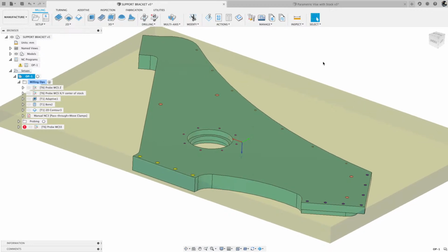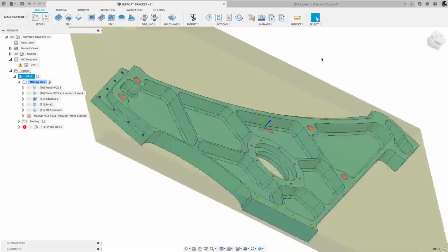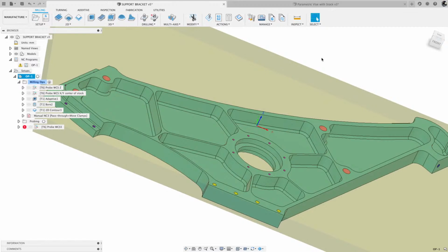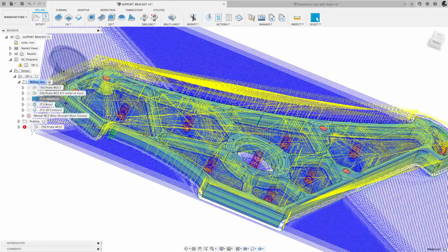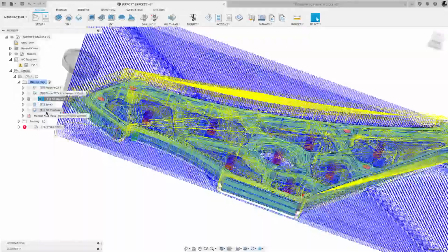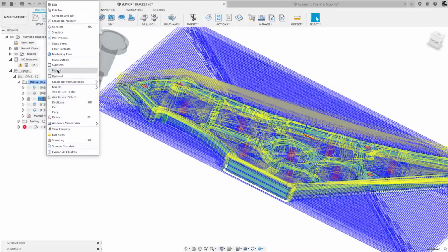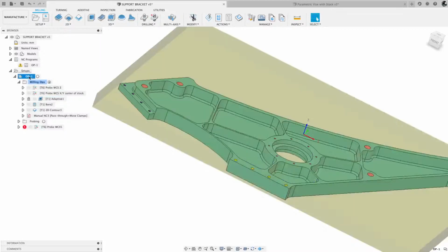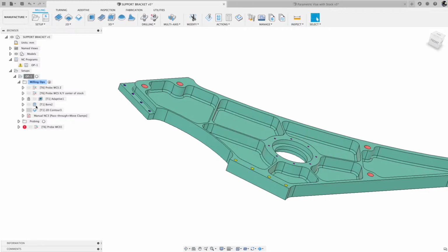But what I can do now is we can touch on this part in the last 7 minutes that we have. So we machined this. I'm going to protect it, so if I make any changes, it doesn't blow up that toolpath. Not sure if you guys were aware of that, but if you right mouse click, you can protect an operation, or if you click on the setup itself and right mouse click, I can then toggle that.